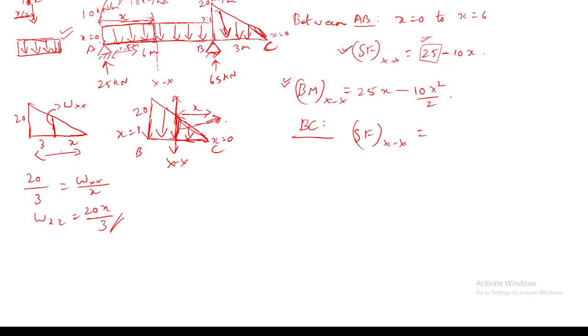Based on this, can you say what will be the shear force? Now I know the load is 20 into x by 3. So what will be the shear force for this section XX? Half into x into 20x by 3. Yes, half into x into 20 into x by 3, which will be 10x square by 3. And whether it's positive or negative?